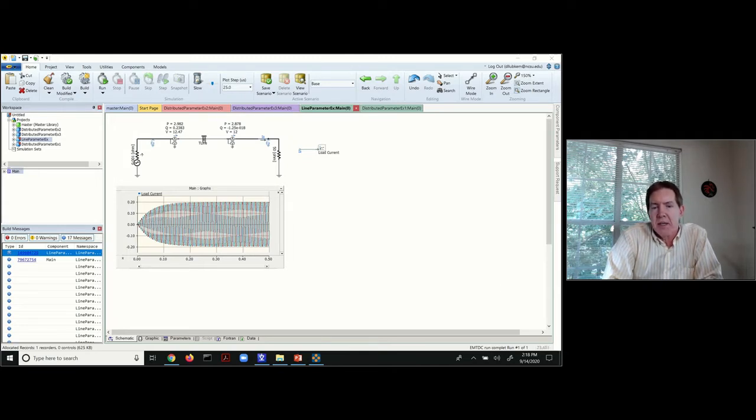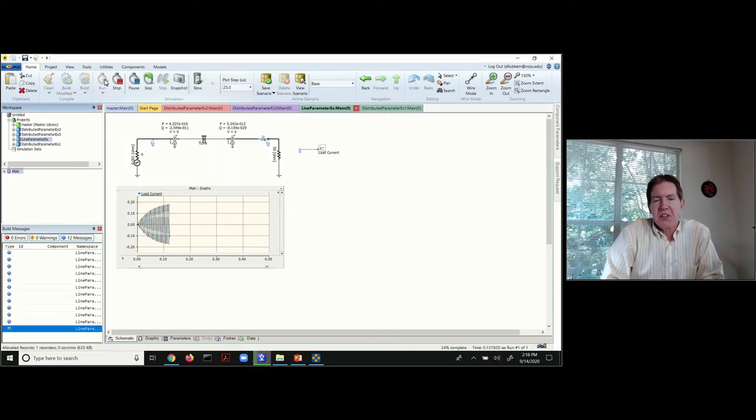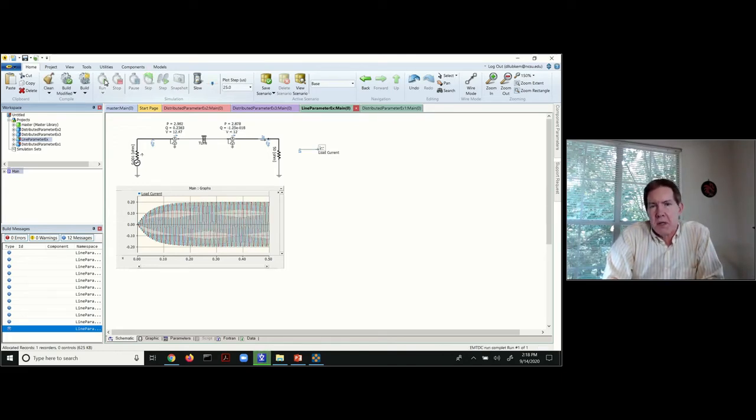What I did is I went ahead and built a line model based on having all the detailed type of information. The simulation is basically just a dummy simulation where I've got a source, and I'm looking at the from and end sides of the line measuring voltages and current, and I have a load on the circuit in order to give me a voltage drop.